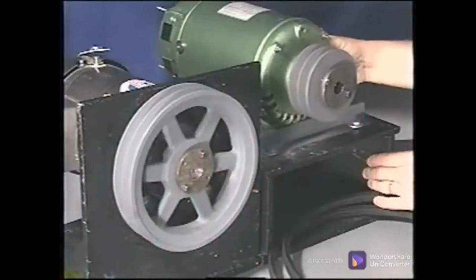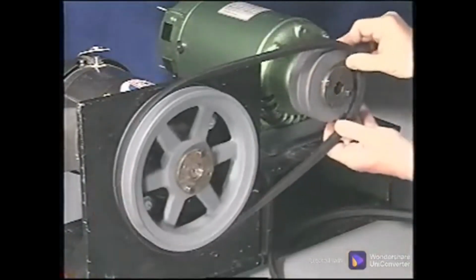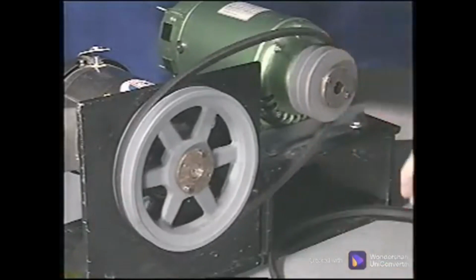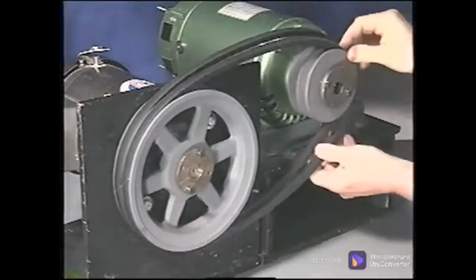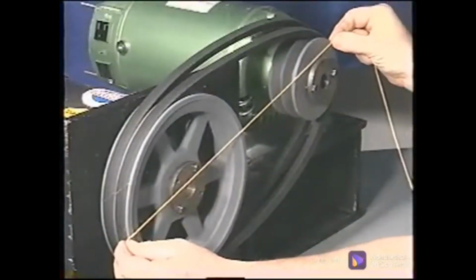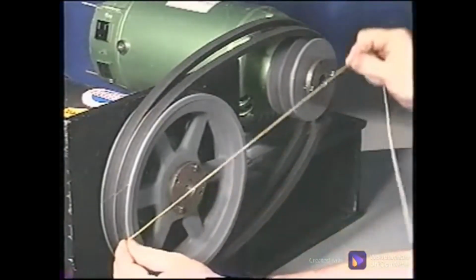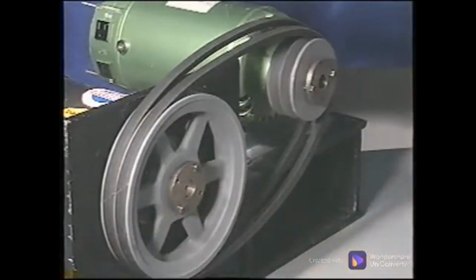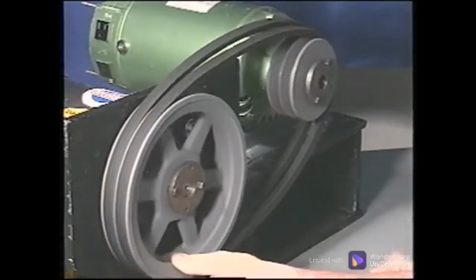When installing the belts, the movable component should be moved in so the belts can be placed on the sheave by hand and without prying them on. Prying the belts on breaks the wrap, the reinforcing fibers and reinforcing cords, severely reducing belt life. These belts should be discarded. Position the motor laterally so the sheaves are aligned, and if your machine has adjustment bolts for lateral movement, secure them as a guide. Verify that the alignment is good, rotating the shaft to ensure the sheaves are true.